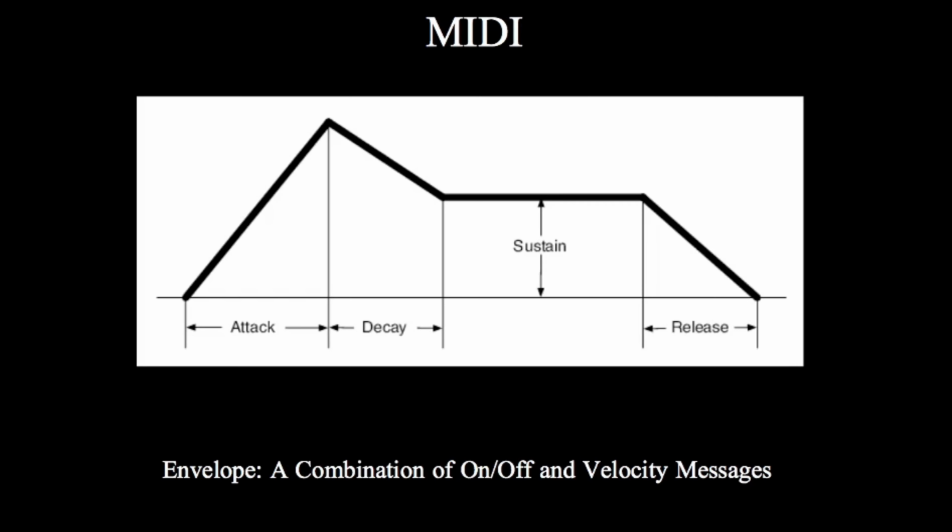What MIDI allows people to do is to make the control coming from the piano keyboard much more like a piano. In other words, you can send more information. So when we're looking at a church organ, the information that's coming from the piano keyboard is only on and off messages. It's only: play this C sharp at this time, stop playing it. In other words, let air through this pipe, stop letting air through this pipe. That's the only set of information that can come from the piano keyboard in an organ, on and off. With MIDI, you're able to communicate both on and off and how fast the key is being depressed. And you can, of course, convert the speed at which the key is pushed down into loudness.